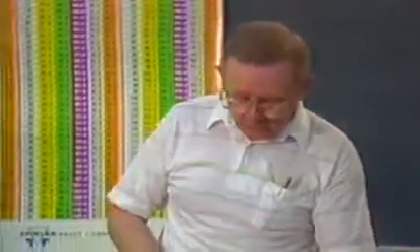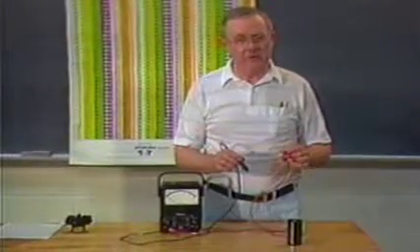Now what we don't know about this capacitor is the value of it. This capacitor is rated in microfarads. It says here 145 to 175 microfarads. This is a quick field check using an instrument that you would normally carry on your truck to check a capacitor in the field with.